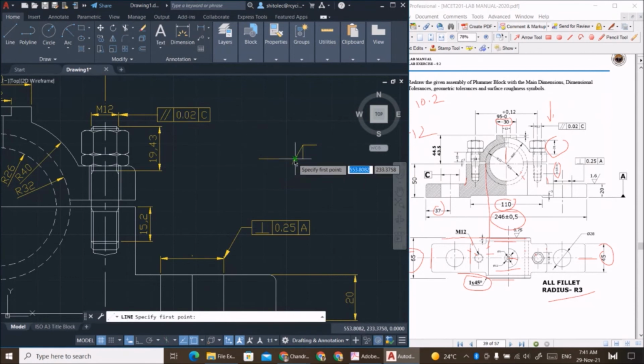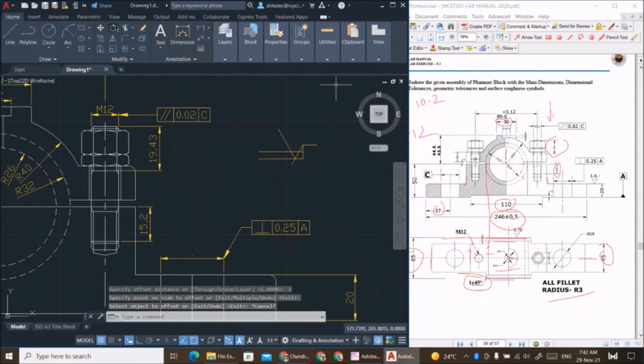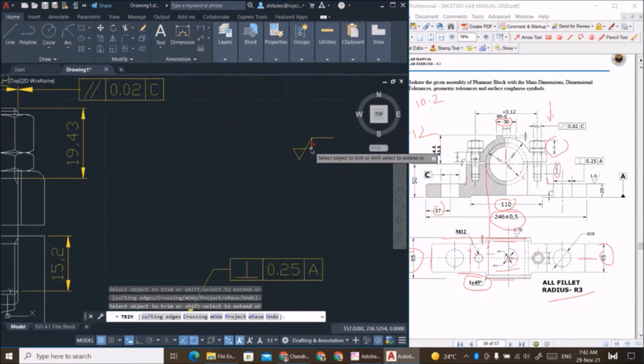Now from this point, okay, tab, 120, enter. And now I will offset this line 3, offset 3. So now it is ready, trim. This is 6, then total height is 6. This is inclined, vertically 6, and this is 60 degrees, and this is joining.